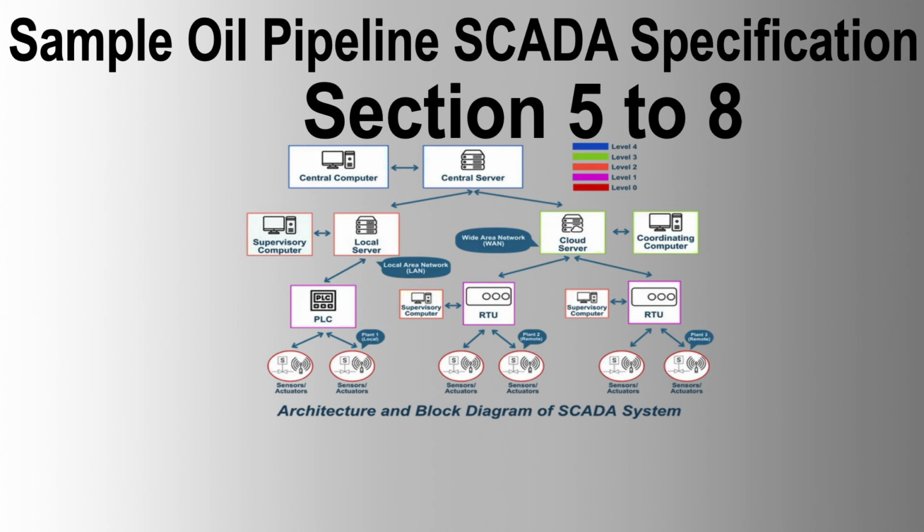7.9 Control and logic functions. Control and logic functions shall be based on a library of standard configurable functions sufficient to execute all functional control requirements. Library includes continuous control functions, manual auto stations, adaptive and feed-forward control, calculation functions, signal transfers, sequence controllers, function generators, logic functions, and data manager suite of software routines.